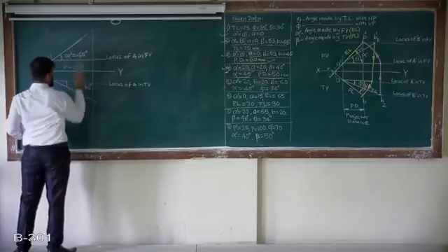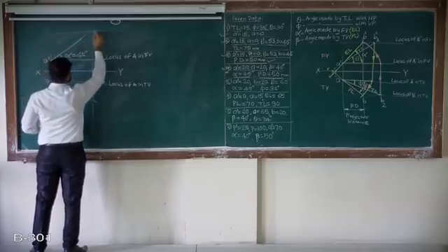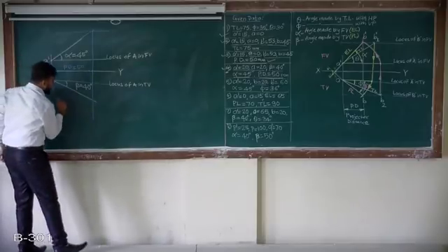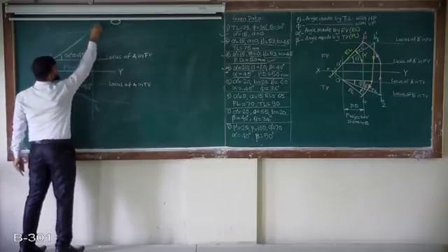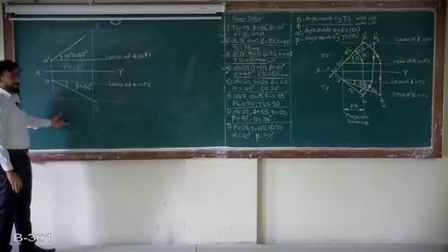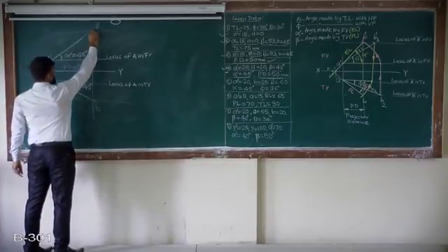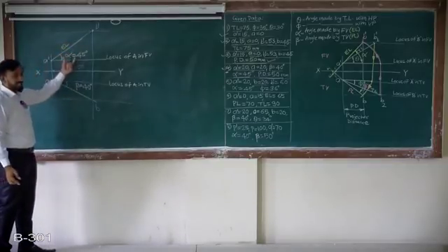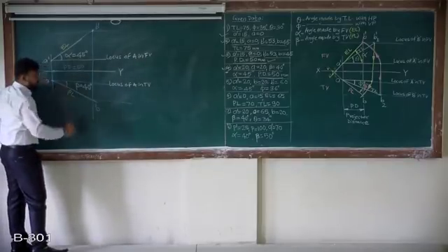Extend this alpha line and beta line. Wherever this projector line cuts alpha as well as beta, we get the corresponding point as B in top view, B dash in front view. Now again same problem. Once you get the locus, how to get the true length? Rotate this elevation length, because alpha is the angle made by front view, so the corresponding length is EL. Beta is the angle made by plan length, so it is PL.